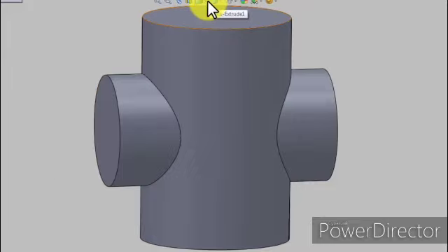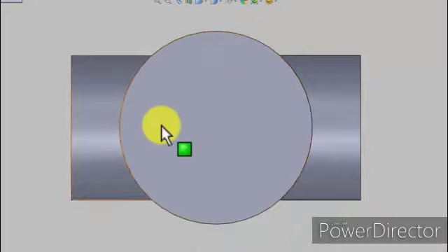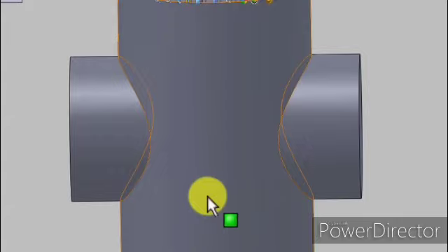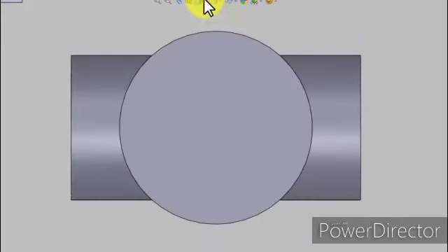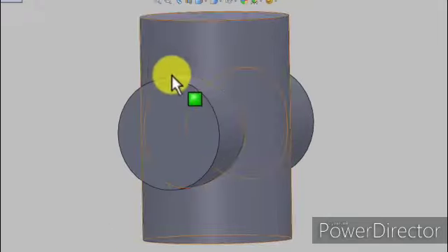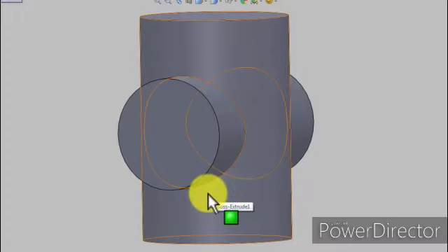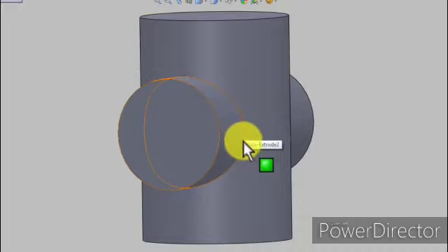When you look at this entire scenario from the top, this is exactly what you're going to see. This is the axis of the horizontal cylinder. This is the axis of the vertical cylinder. Both of them are bisecting each other, and this was the top view. And when you look at this from the side, it's going to look something like this. This is the left hand side view, to be very precise. Now guys, you can see that this is the curve of penetration, and I'm going to be positioning points over here in the form of say P1, P2, P3 and so on.